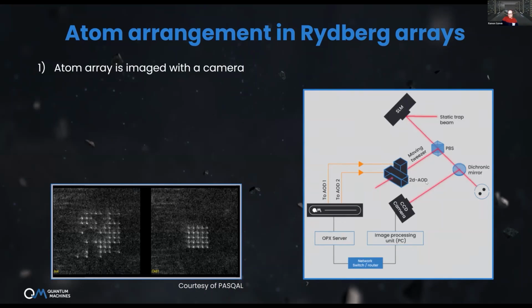I don't think I'm telling you anything new here. And so these AODs are connected directly from the OPX. The only thing you need to add is amplifiers. The OPX outputs 4 dBm max. So to drive AODs or AOM, you need a 30 dB gain here, which we currently do not provide. But we do provide the AC signal directly, of course.